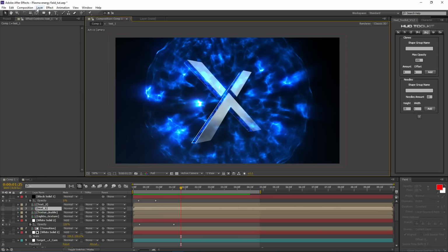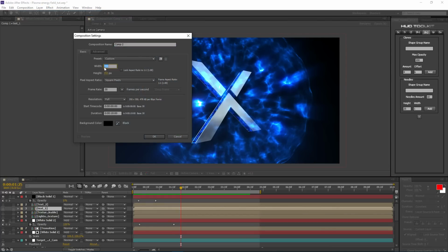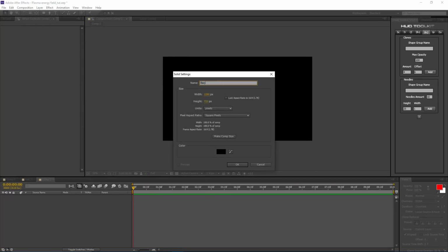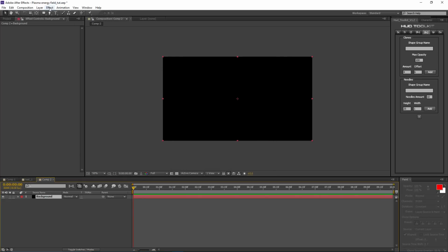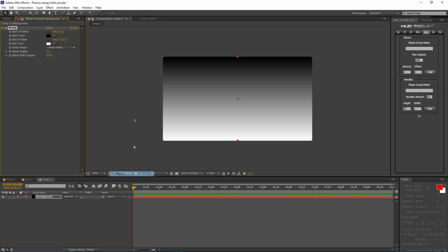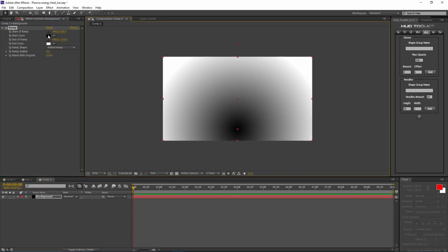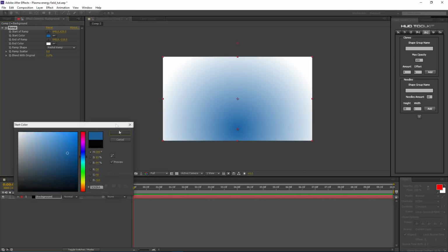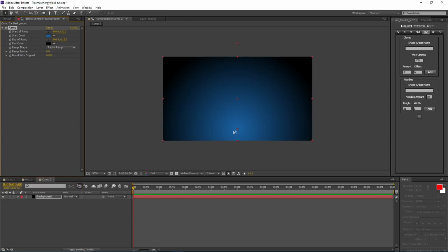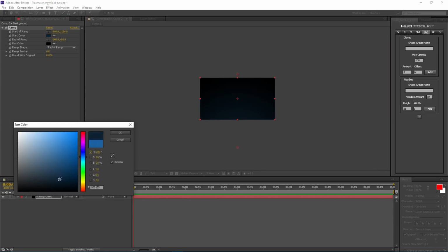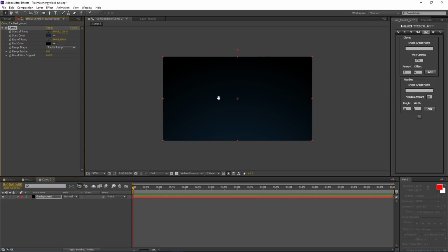Alright, so let's get started. I will make a new composition. Let's go for 720p and let's make this 10 seconds. Okay, and let's start off by creating a new background. So I'll just make a new solid and I will go to Effect, Generate, and make an interesting background over here using a ramp. Let's actually make this a little darker, and you can make your background however you want.